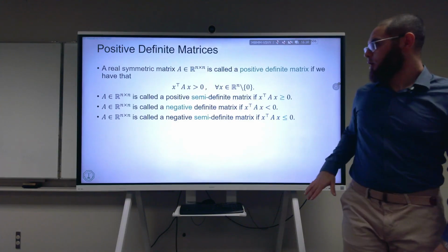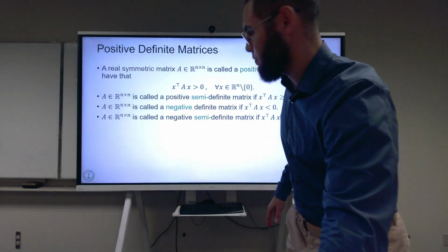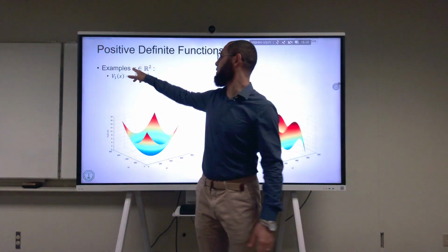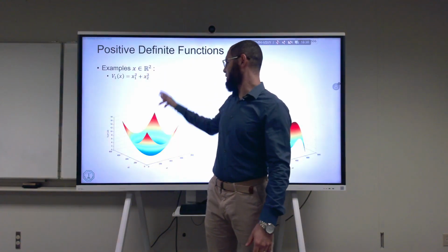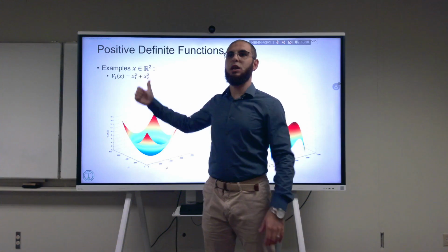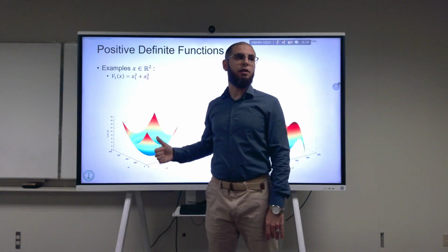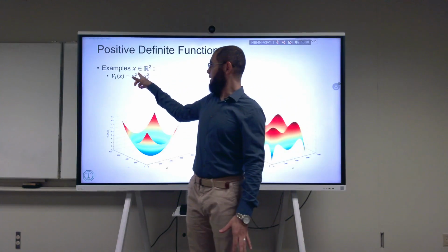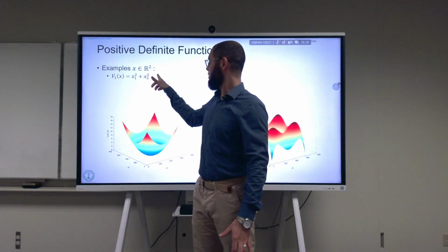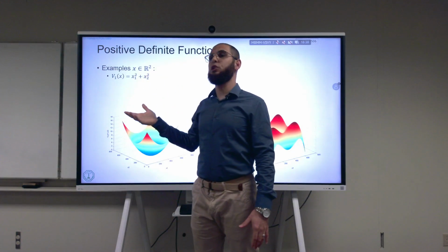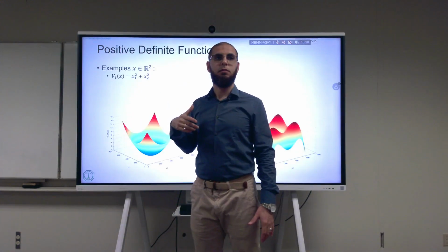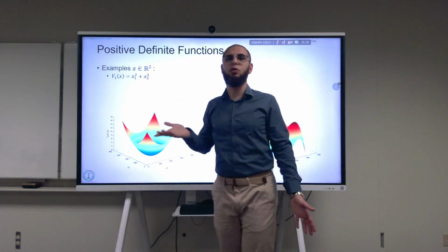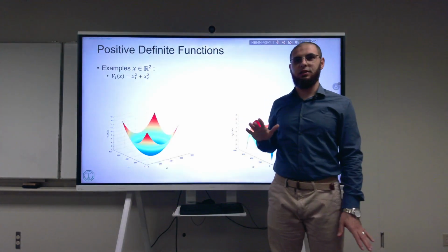That's an excellent point. Let's go back to the parabola actually. Take this function, x1 squared plus x2 squared, and then add to it some c. So what happens to this curve? It goes up. So what's the Lyapunov function that you can define? Let's assume that the function you're talking about was x1 squared plus x2 squared plus c. What should be the function I should use for Lyapunov? The function minus c. So I just shifted back. You can always do that, right? So it's a very easy check.